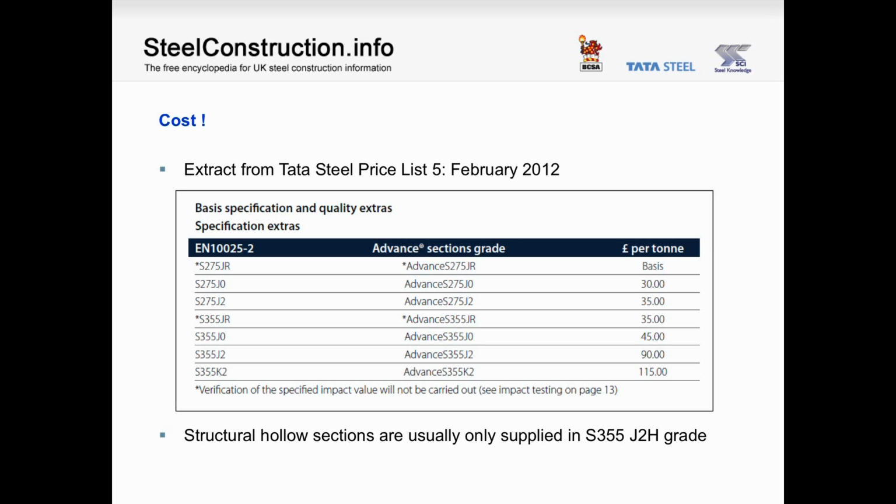At the start of the presentation, I mentioned that S355GR is now the standard grade for structural steel. So this is the main grade rolled at the mill. And perhaps more importantly, the only grade kept in stock by stockholders in any significant quantity. That means if the project requires anything other than S355GR, it will need to be ordered direct from the mill, and the mill rollings are every 4 to 6 weeks, and this would need to be accommodated in the construction programme.